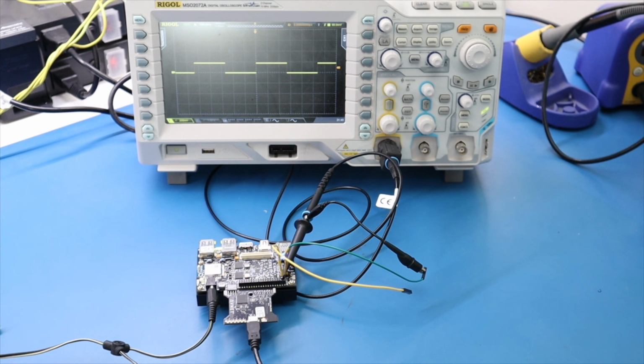To me, it's not technically level shifting, because if I'm level shifting, I'm going from like TTL to CMOS, or I'm going from one chip voltage to another chip voltage. For this, we're going to need to power shift, if you will, because we're going to need all the current that we need, and we're going to need all the power that we need to drive an LED. And if you do it that way, then ultimately you'll be able to drive as many LEDs as you want, as long as your power supply and all that other stuff can handle it. So keep an eye out for that video. It'll be coming up shortly.